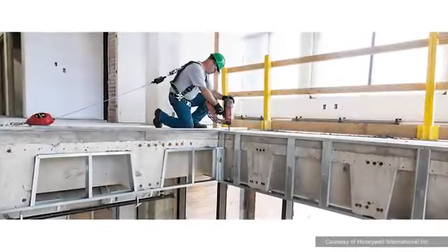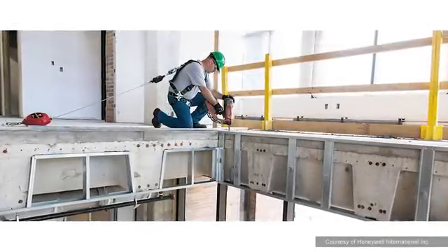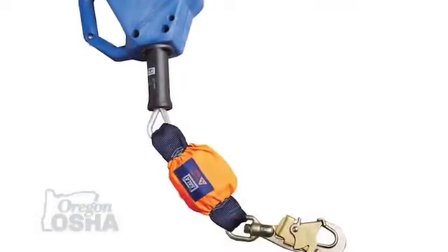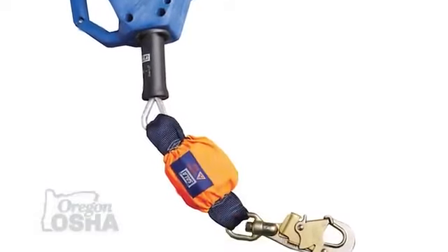Leading edge we would define as any place where, when a worker's tied off with a fall arrest system and they take a fall, their lifeline, whether that's a rope lifeline, a cable lifeline, or their lanyards, could strike that edge, and the anchor point is going to be on one side of the edge and the worker is going to be on the other side of that edge. When we're working in a situation where we have a leading edge, we have to make sure that our arresting device stays with the worker themselves.